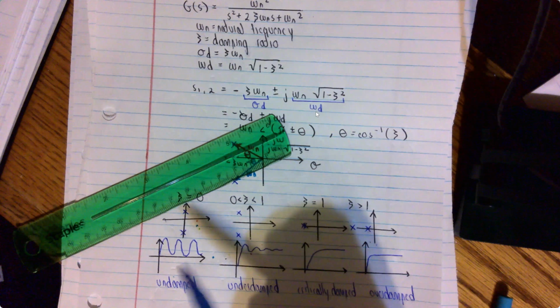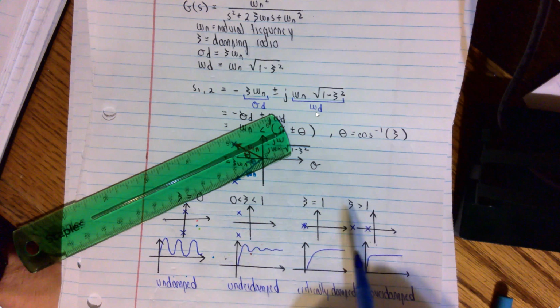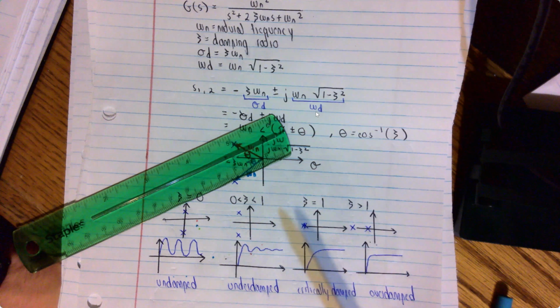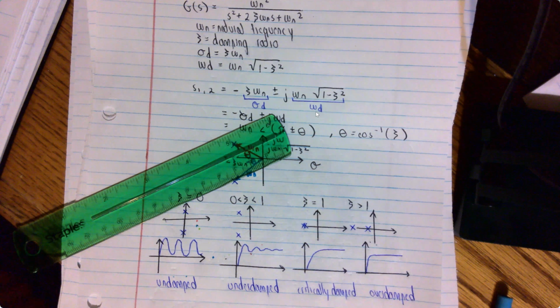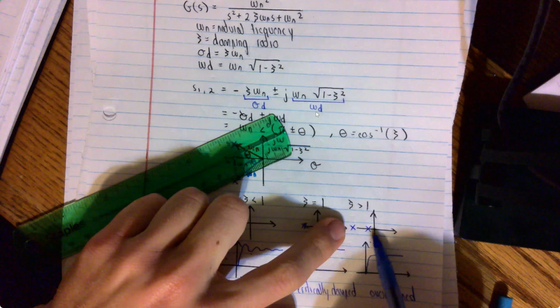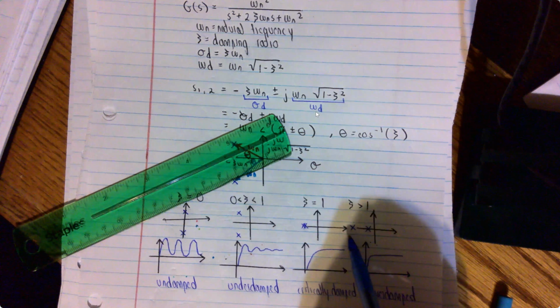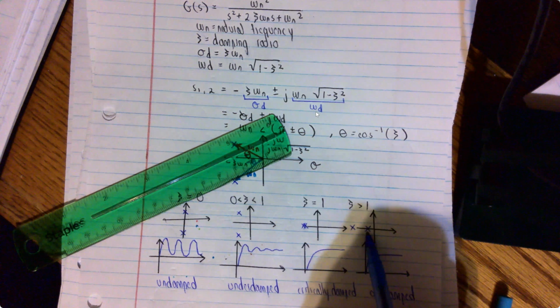We're not along the imaginary axis anymore, so we're going to have real roots for our denominator. They're going to be further apart, so you can just estimate it by the pole that's closest to the j omega axis. So you can convert the second order into a first order system just by using the simplification.